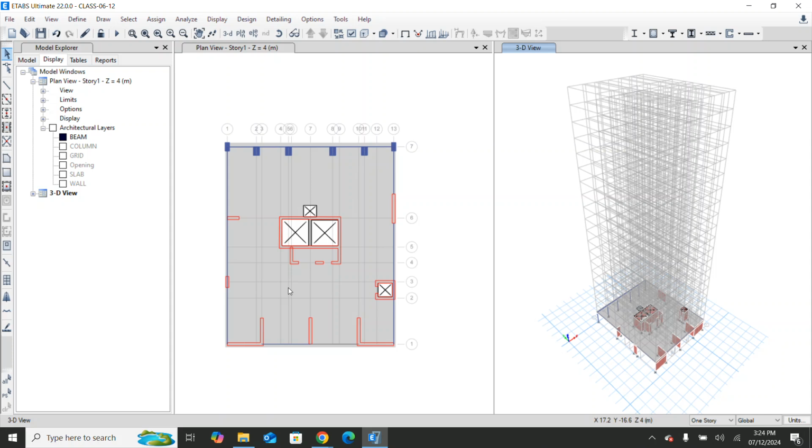Okay. But wind load we did not assign, madam. Yes, we'll do that according to the building. Wind load also I'm going to assign over here. 105 mph wind speed I'm going to assign. Okay, this is what I want to do.